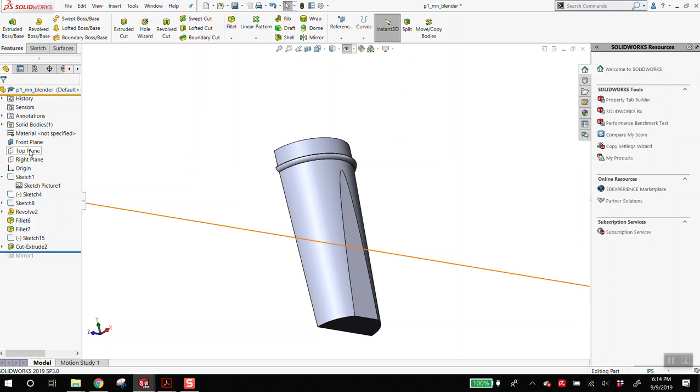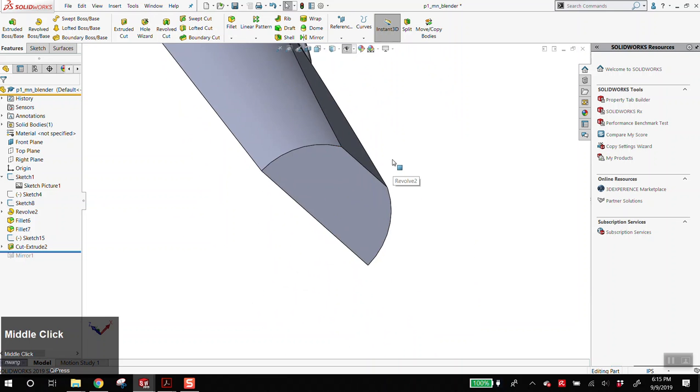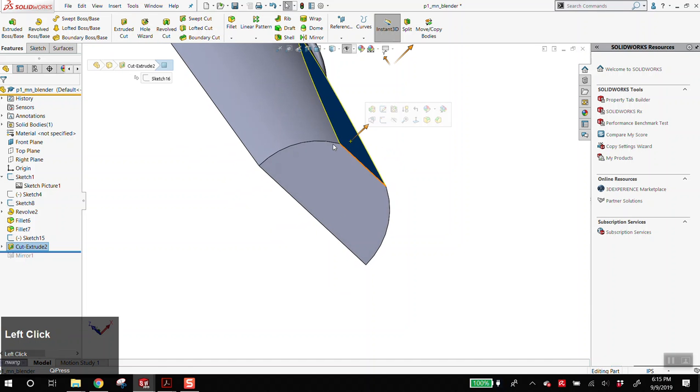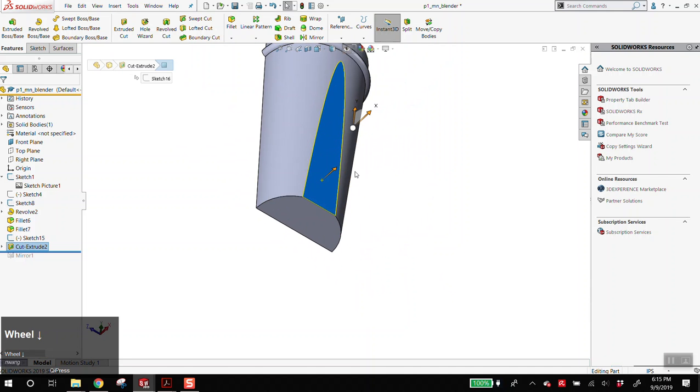You know what? I'm sorry, I don't want to get into it. There's a lot to it. You have to essentially create a plane or a face that's perpendicular to this, draw a sketch on there of the bumps, and extrude those bumps up. It's a little bit trickier, though, because of this curvature through here. So we're going to save that for Wednesday and get to it then. Sorry, Max, but good question.